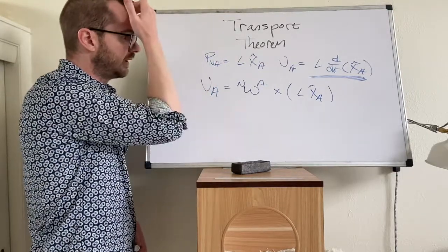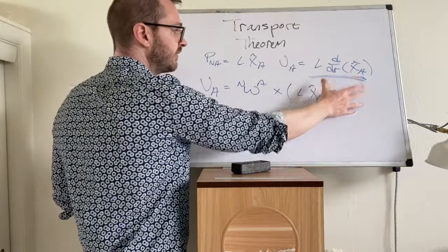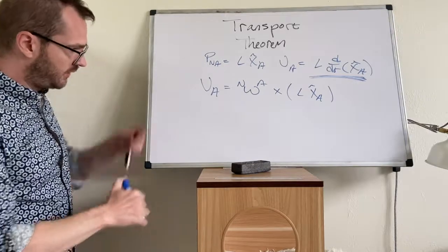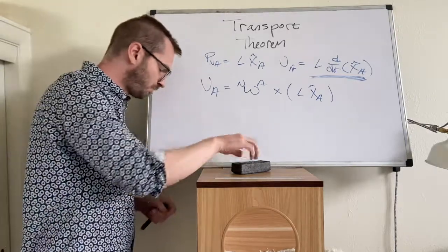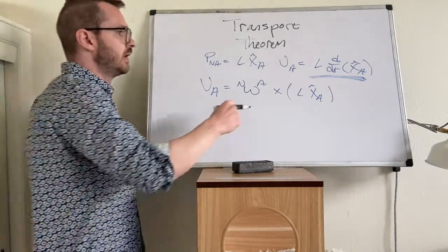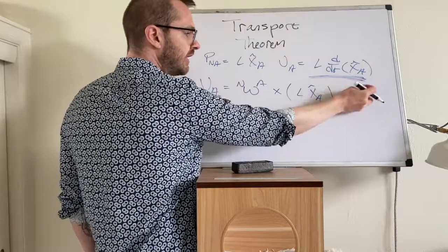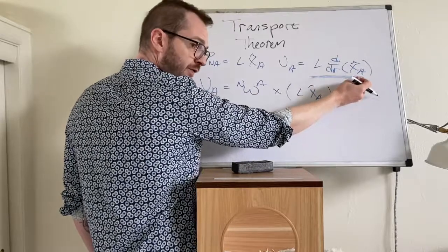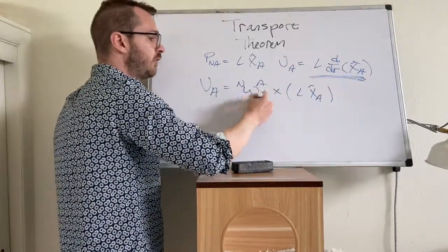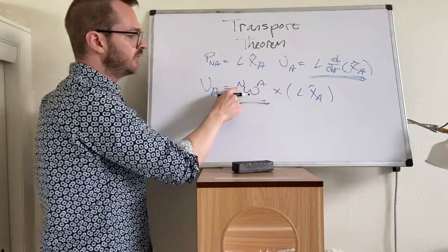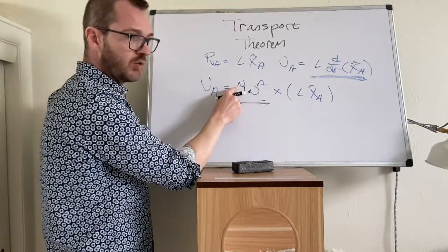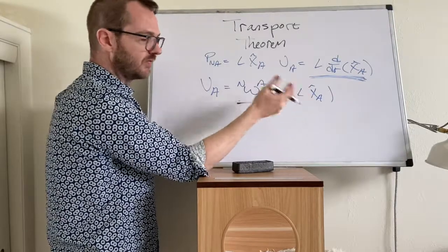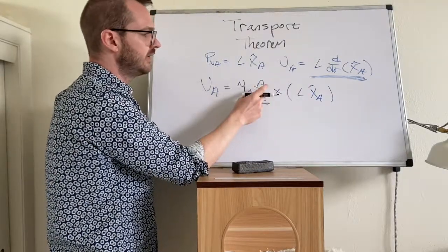Okay, so this is it in practice. We had this term, and we're going to replace it with this term. Here's where these pieces come from. First of all, what frame are you taking the derivative of? In this case, we're taking the derivative of the A frame. Therefore, when I write angular velocity, I do it from N, and it's always from N to A. We're going to do some examples where we take derivatives of other frames, so we can see that in practice, but N to A.